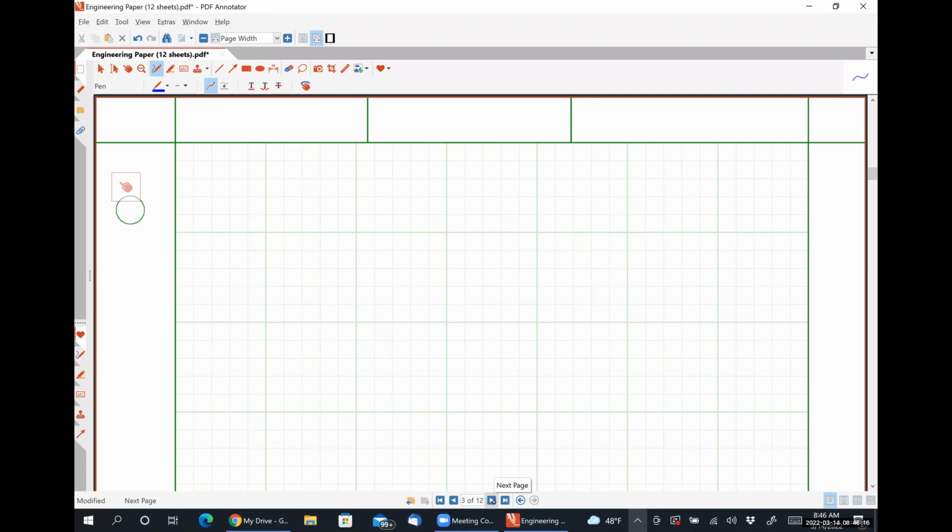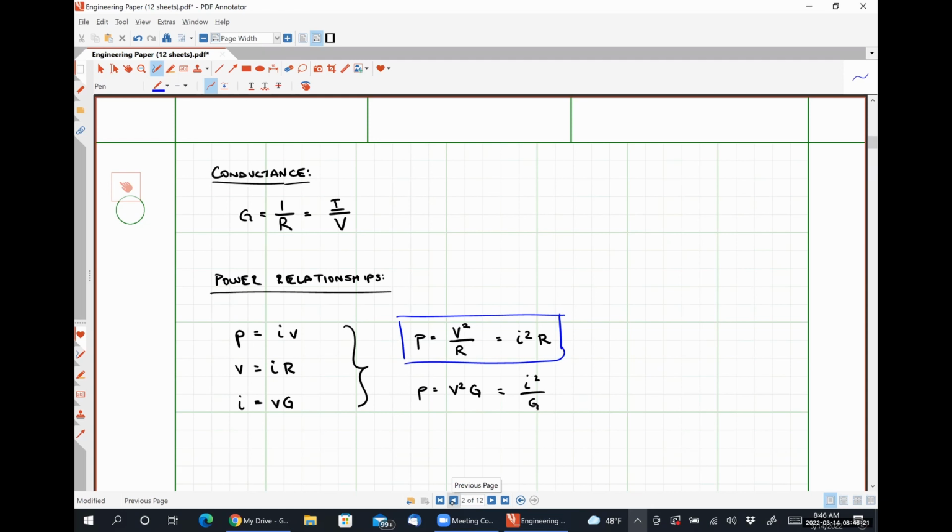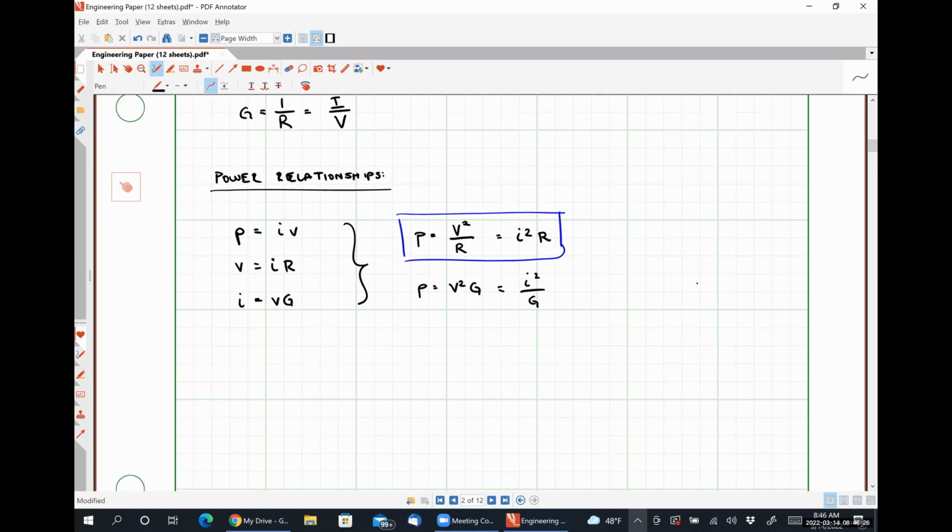Are you going to give an example of the conductance thing, of making the reciprocal and using it as a resistance? Absolutely. So let's say that we have the following circuit element, and let's say that it has a conductance of 5 millisiemens. Here's another thing that's slightly confusing about conductances. They have the exact same schematic symbol as a resistor, so you can only tell the difference by the units.